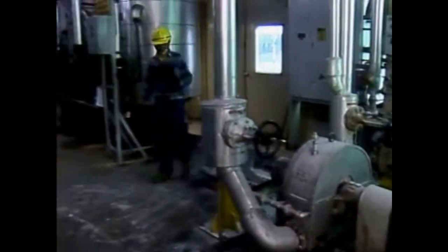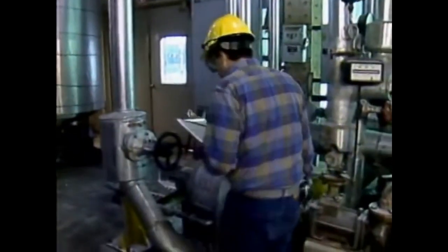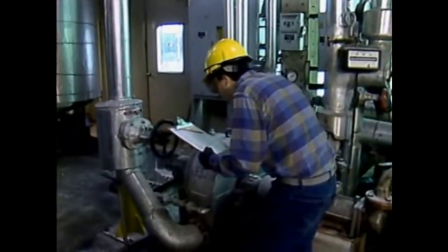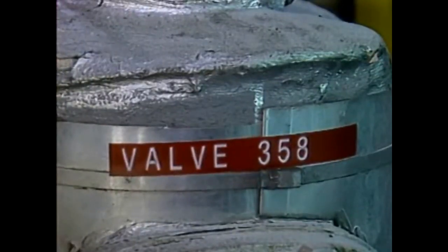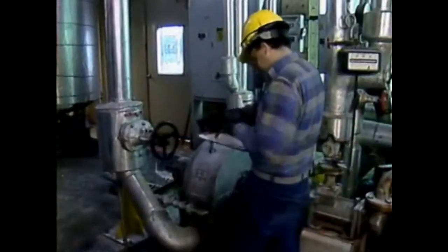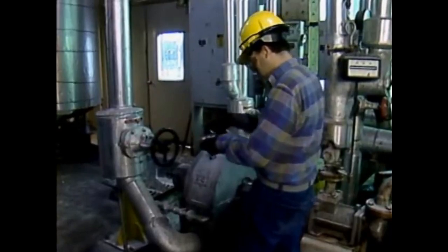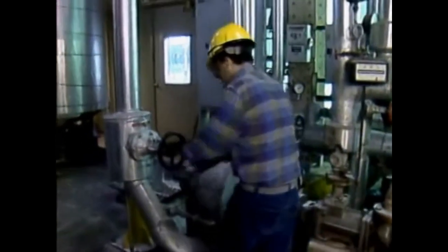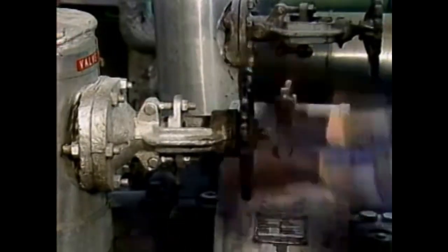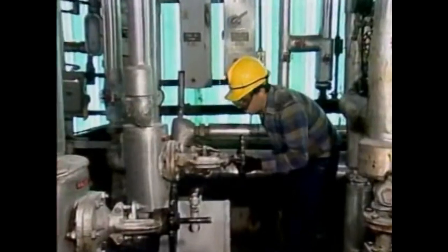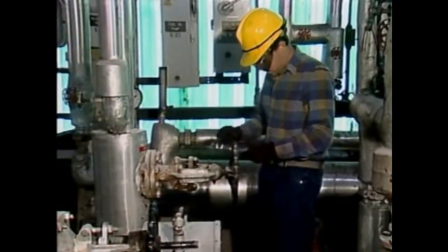When performing a valve lineup, an operator would use checklists and piping system diagrams to verify valve identifications and positions. Valves are usually labeled with ID numbers that are also shown on checklists and diagrams. By cross-checking the number on the valve label with the number on the checklist and the piping system diagram, an operator can make sure that he's at the right valve. The operator can then position that valve as specified in the checklist. These steps should be repeated for all the valves on the checklist until the valve lineup is complete.